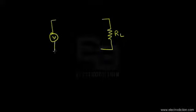Let's say we have a voltage source of about 16 volts. Now we require that the voltage across this load resistance be kept constant. This could be achieved by a Zener diode, if we connect it in parallel with the load resistance.